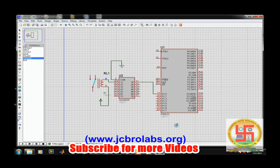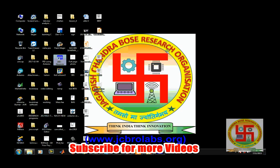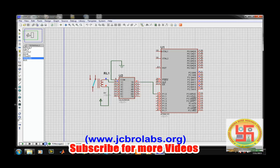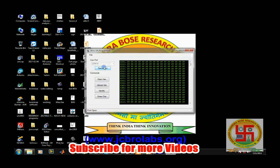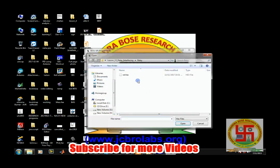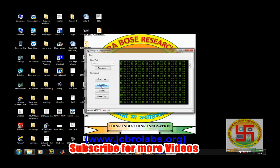So now let's burn the program onto this microcontroller, to the processor on this programmer, and then connect it, and identify the microcontroller. Now it's identified, open the relay hex file, and then upload it. So once it is uploaded, our programming is done. Let's wait for some time to see whether it is working fine or not.